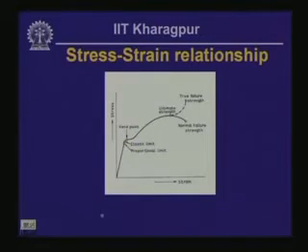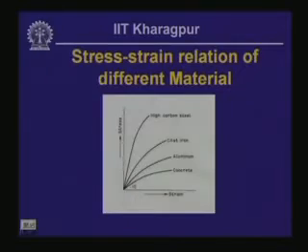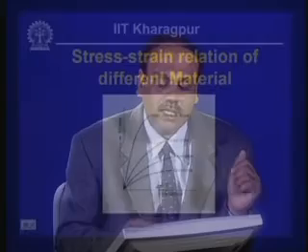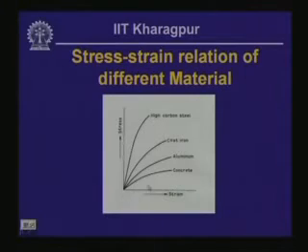But as we have seen in the subsequent figure, we do not have any defined yield point. In strength of material, when we deal with the stresses within elastic limit, we need to know the value of the yield stress beyond which the member will start yielding. So, we try to limit our stress up to the elastic level. We need to know the value of the yield stress, but from this kind of stress strain distribution, it is difficult to know it.